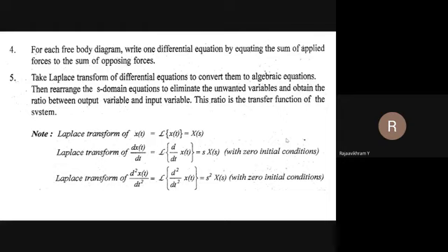Why are we using Laplace transform? It simplifies the differential equation into an algebraic equation. So the differential equation is simplified as an algebraic equation so that you can rearrange the order of the system and easily get the output of the system divided by the input of the system.